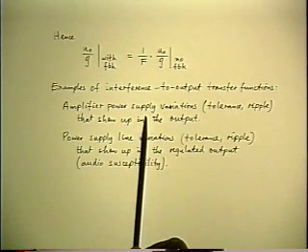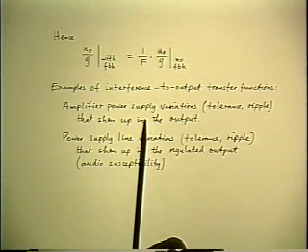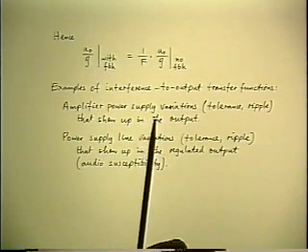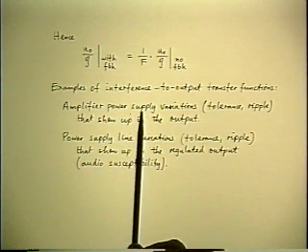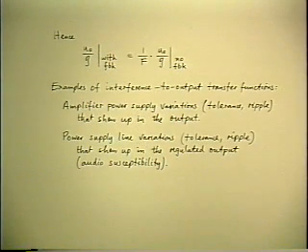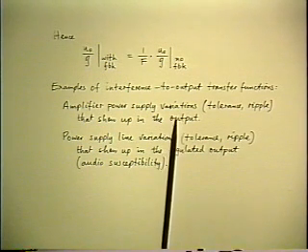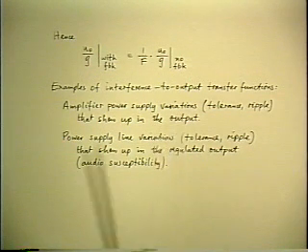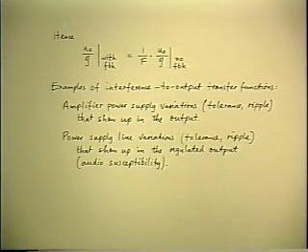The interpretation of the interference signal is where this becomes useful, and it has lots of interpretations. One of them is that the interference may be power supply ripple. It's just another input that comes in part way down the amplifier string. It may also be thermal noise, which mostly comes in the first stage.